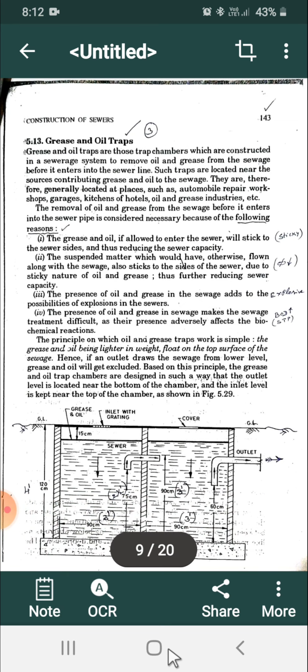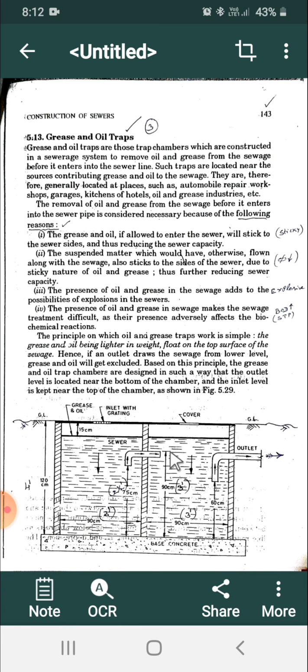Here, this is different. See, here directly the wastewater which is coming along with the oil and grease will float like this. See, there is a free board here. The free board means this one. And what is the height of this structure? Everything has been given. And here also the distance between the outlet and the bed of this tank is given. Here, why it is bending means the oil and grease will be floating here directly, so that it cannot enter. It will go directly and float on the surface, and that will be removed separately.